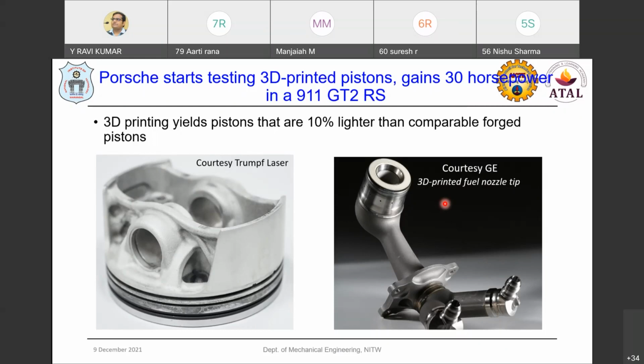You can go for casting or forging, or machining or any other conventional manufacturing, but because it consists of so many complex parts and very fine nozzles, very fine holes, it is highly complex and difficult to manufacture with conventional manufacturing. And even to manufacture and assemble those 34 components, it will hardly take less than 6 to 8 weeks. But with the advanced metal AM process, you can manufacture this component in 8 hours.